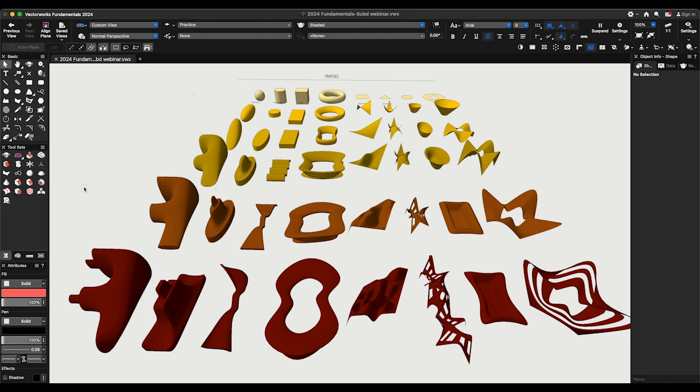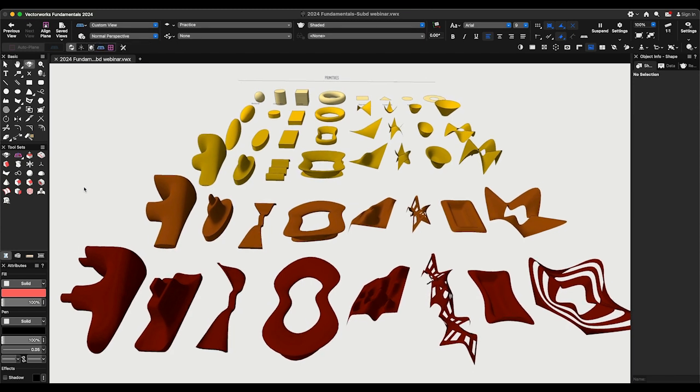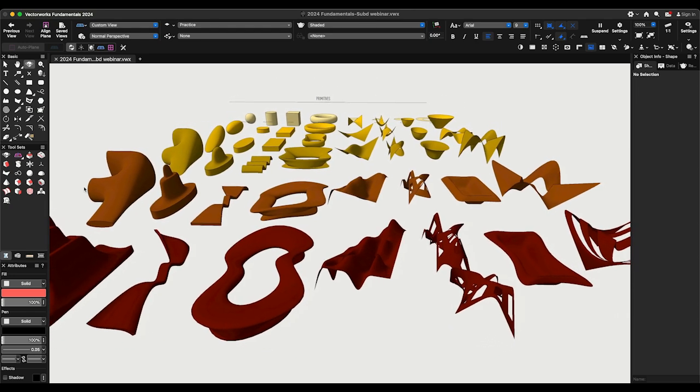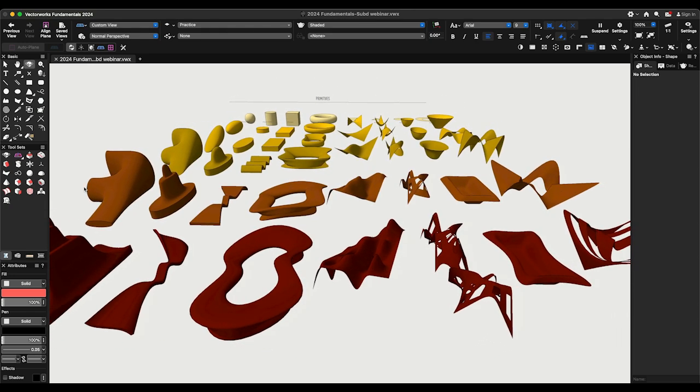Start with a sphere. Make sure you include all of the modes, and in no time, you'll find yourself feeling comfortable manipulating new shapes. Depending on your type of projects, you'll find that some of these modes will become your favorites. For me, creating furniture content requires a lot of splitting edges and creating wrinkles.